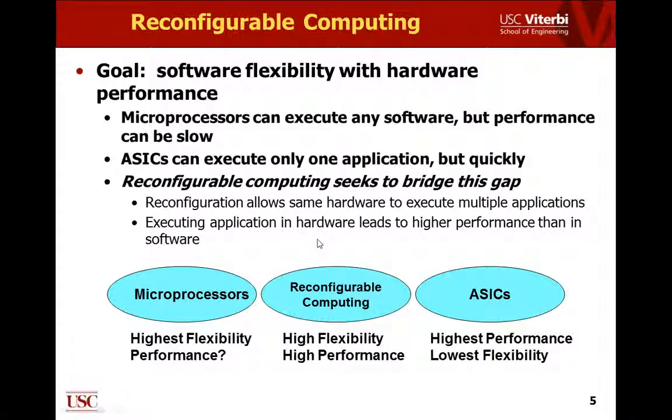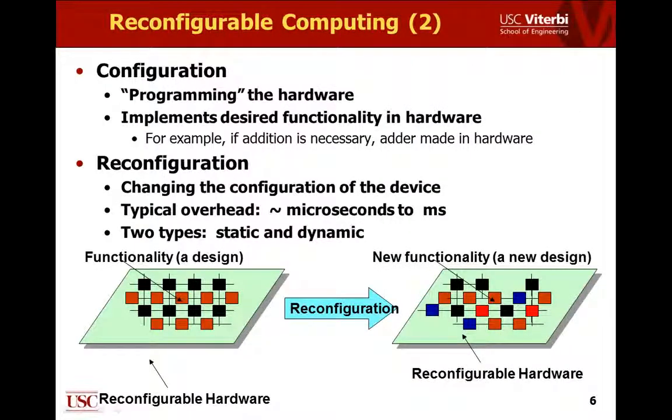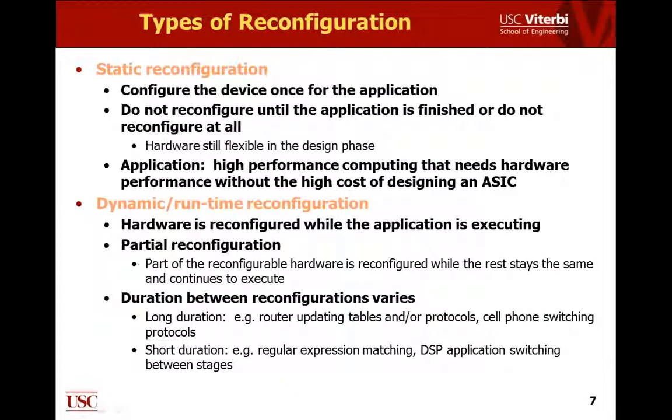particular application we have. So in this context, reconfiguration here means going from a particular configuration in which you have a particular functional unit set up on the device to configuring that to solve an alternate problem by changing the configurations. For example, the logic may be configured to perform an arithmetic operation like multiply. After a few cycles, you might want to configure that to perform an add operation. This is what we mean by reconfiguration. That means at runtime, we realize various functionality by being able to configure the basic units, the operational units, of these FPGA devices or reconfigurable devices.